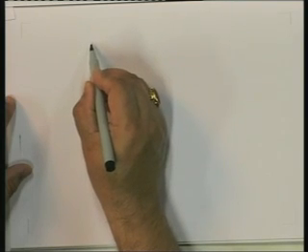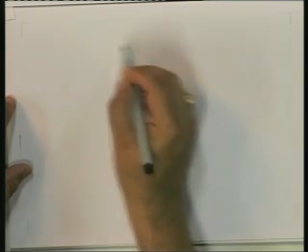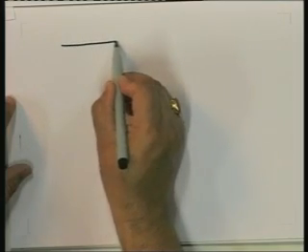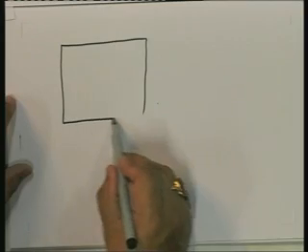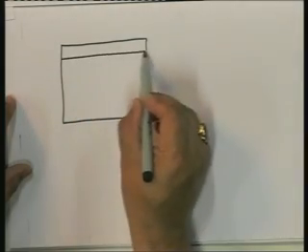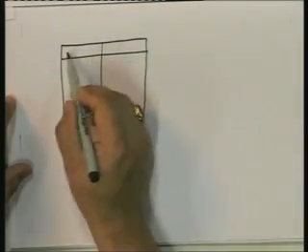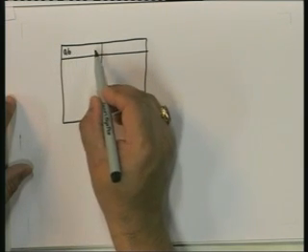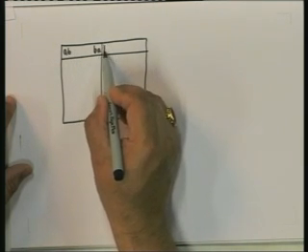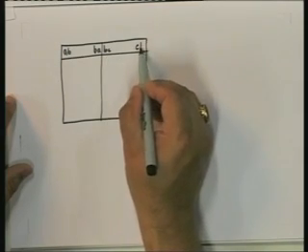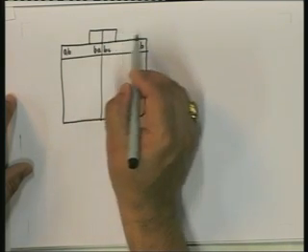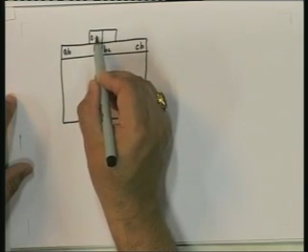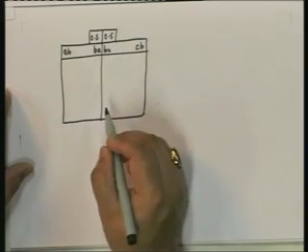So I'm going to apply the moment distribution. Moment distribution is simple. Go back and look at your notes. You will have A, B, B, A, B, C, C, B. For this, it will be 3 by 4 I by L, 3 by 4 I by L, 0.5, 0.5.